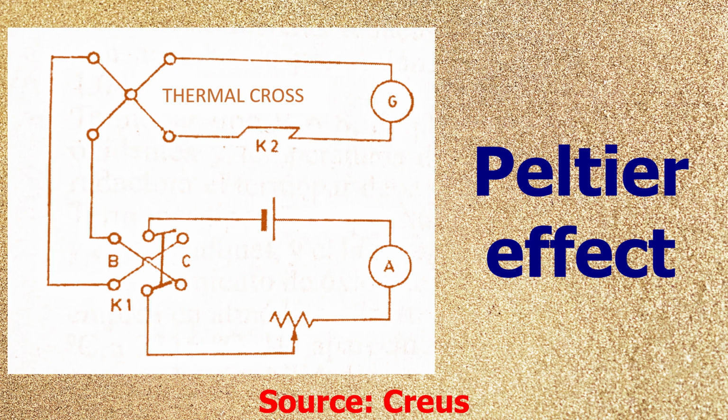It will be observed that by subtracting the ohmic heating, which is proportional to the square of the current, there is a remainder of temperature that in one direction of the current circulation is positive and negative in the opposite direction. The effect depends on the materials that make up the joint.